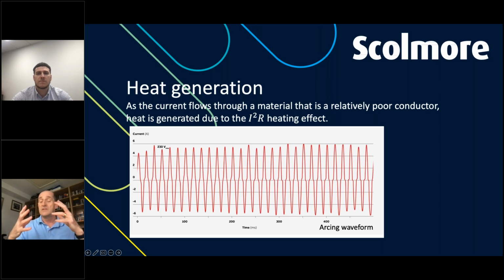So a high temperature at the fault location can cause the path of the carbonized material to vaporize. So you haven't just got a piece of carbon there. This has now turned slightly gaseous, and the arc is now passing through air, through a material that is just floating around in this very tiny space, and heat is being generated. And the waveform that would be created is not too dissimilar to this. And of course, our AFDD now is seeing this type of arrangement, or part of it.